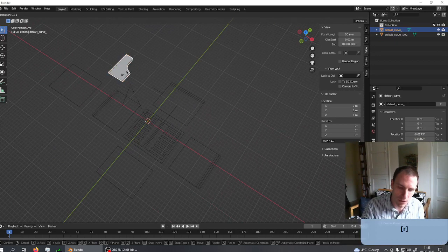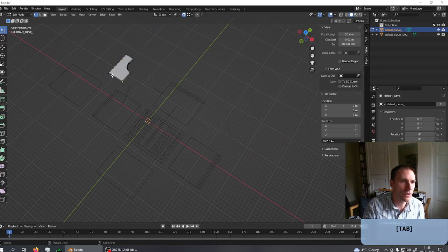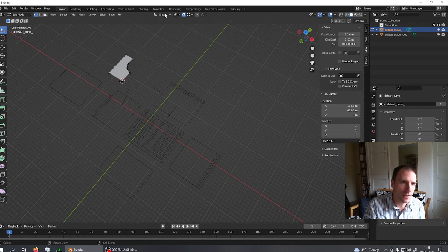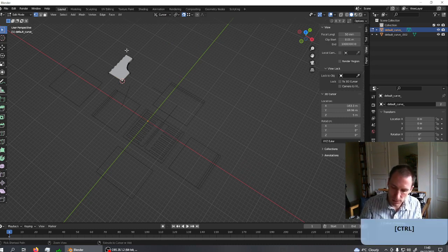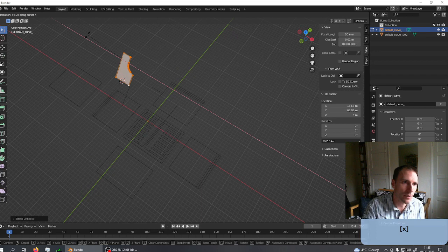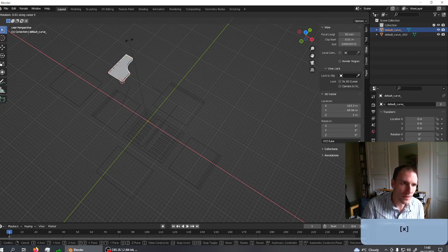So let's go for a rotate. Let's put the 3D cursor there, so snap, and then we go cursor to selected, and then if we do a rotation on the cursor, now if we go for linked, R, X, there we go, that's in, let's go to object mode, there we go, R, X, and it hasn't worked.